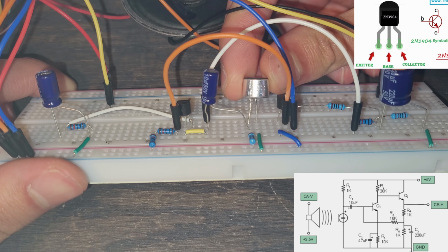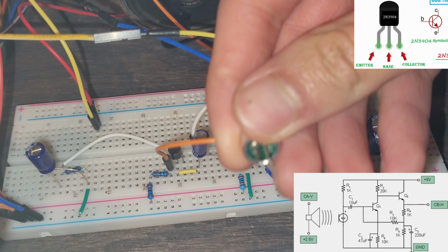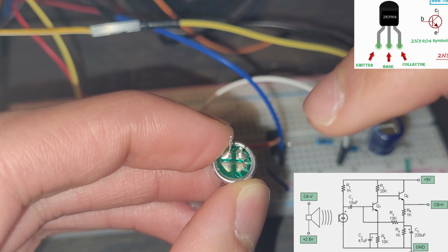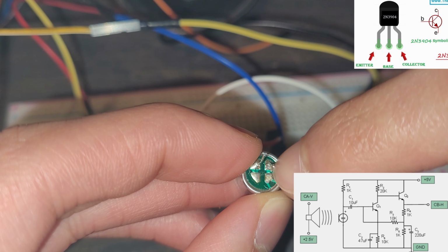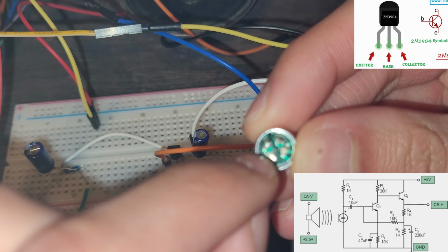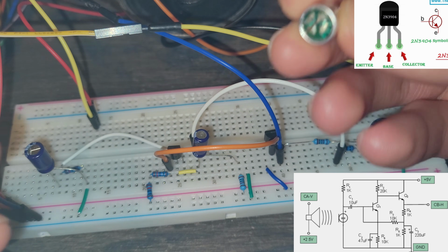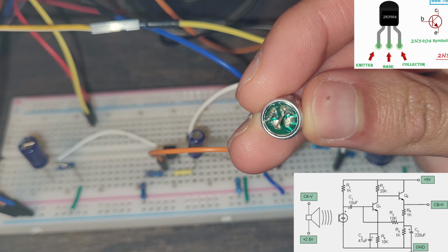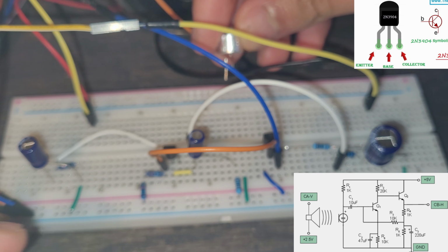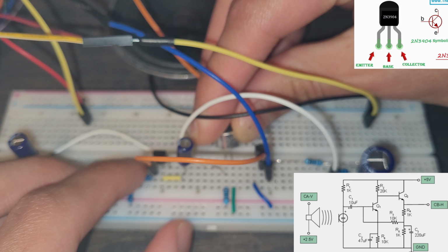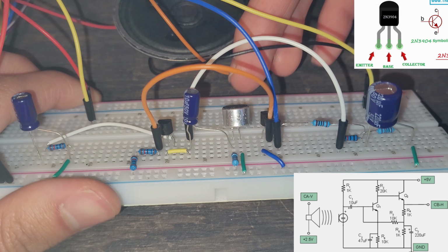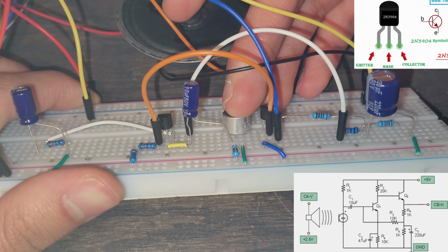If we pull it out like this, we can see that the solder point is on this one, which is connected through this green solder right here. These two are connected, and these two are connected. So that means this is negative and this is positive. So when we wire this up, the positive is going to go inside like this. So we can plug this back in here, the same column as our resistor and the same column as our grounding wire. And we're just going to push in like this.